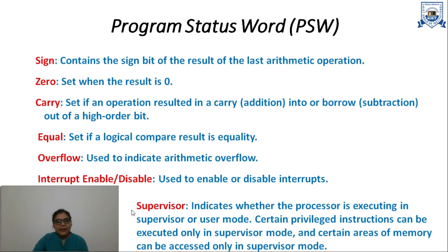This flag is used to denote whether the processor is executing in supervisor mode or user mode, because certain privileged instructions can be executed only in supervisor mode. Some instructions can be used in user mode, some instructions can be used in supervisor mode, and certain areas of memory can be accessed only in supervisor mode.